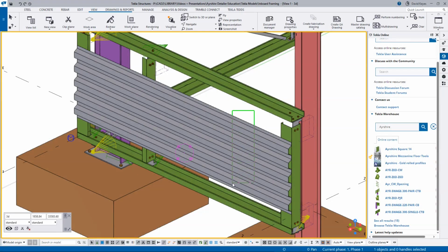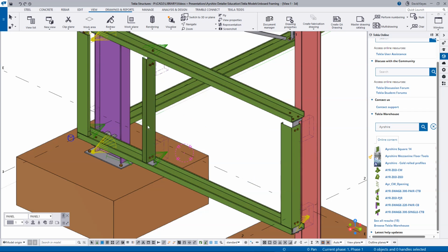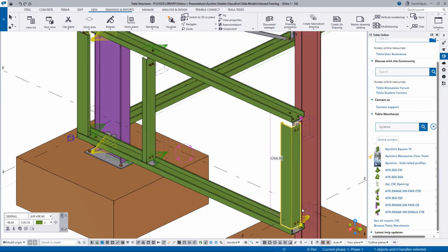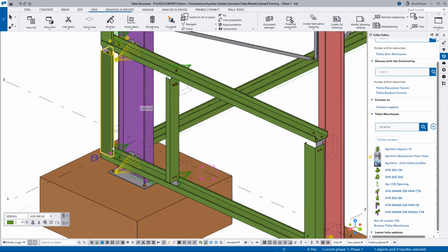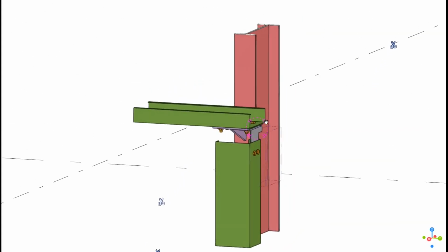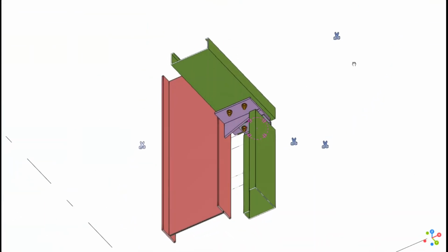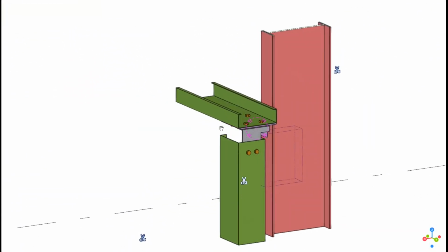Panel joint rails are used at cladding joins and corner returns. PJRs with the bolted flange to the right are modeled from bottom to top. PJRs with the bolted flange to the left are modeled from top to bottom. If in doubt, it's best to make the hole to PJR end distance identical at both ends to avoid any handing issues. Fabricated cleats will be needed for side rail to column connections that coincide with any PJR to side rail connections.